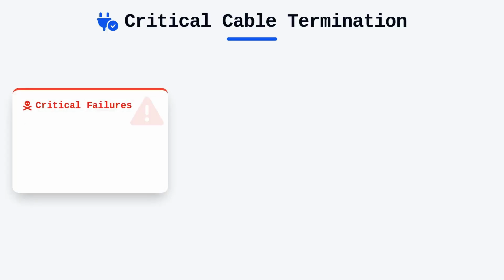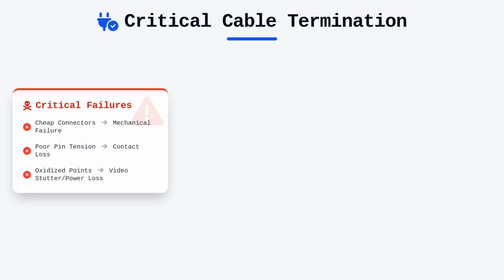Once the cable is routed, the termination process becomes the next critical point of failure in the field. Using high-quality RJ45 connectors is non-negotiable. Cheap, poorly molded connectors often lead to mechanical failure, where the contact pins lose tension or fail to pierce the insulation of the conductor properly.